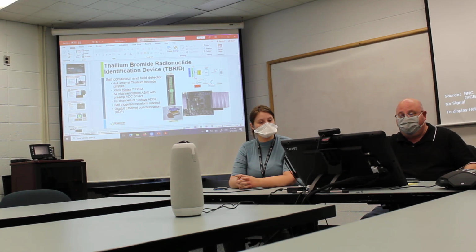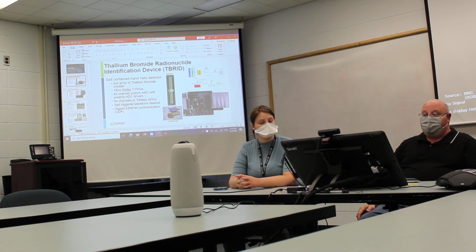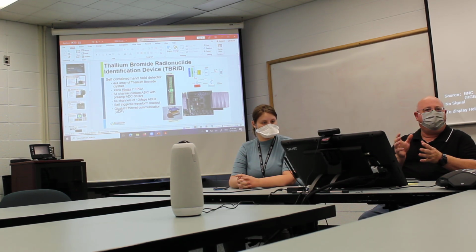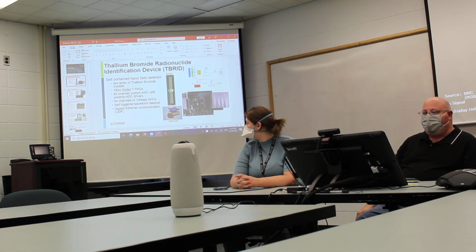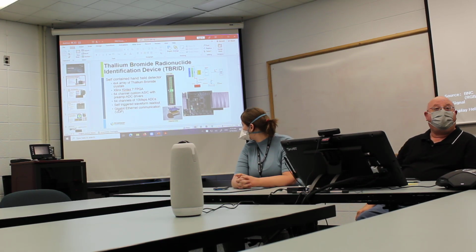It's a self-trigger readout. It self-triggers on each channel. It can also trigger on neighboring channels. So it's a cute little package. You'll see this when I take you on a tour. And all the ADCs are being read out over Gigabit Ethernet.